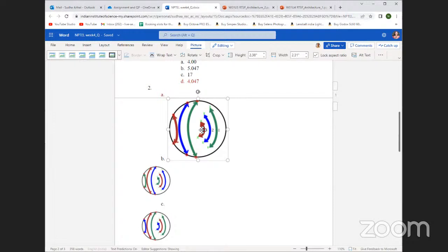I discussed in the class, if you remember, how we cascade the sections, and how you take the combination of poles and zeros to reduce the overshoot that is going to happen, because here they will be cancelling it out. So these two have to be combined. This is what has been found in the literature. The next is combined with the next one a little nearer to 0. And the one closest to our origin is combined with the farthest. That is what the literature gives.